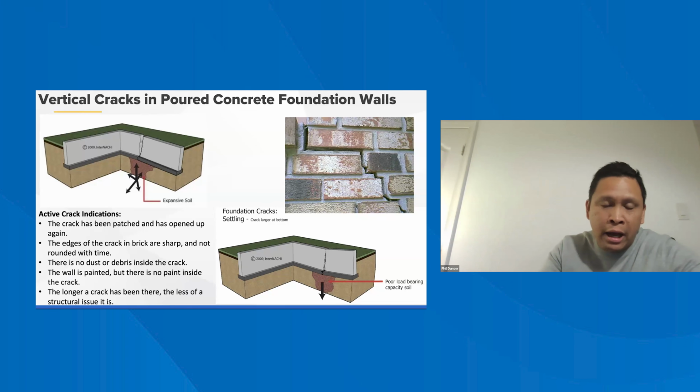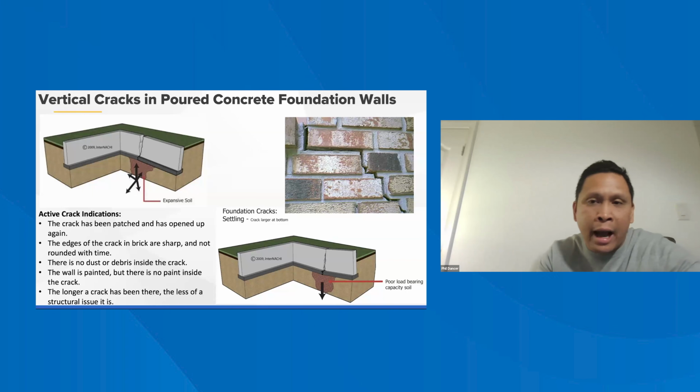So just know that whenever you see unevenness in either of these locations, it's typically not a concern, because the basement floor and the garage floor are going to be independent of the foundation walls, right? It may still not be desirable to the family or to the client that you're helping, but it's typically not going to be a structural concern, because it's just independent of the foundation walls.